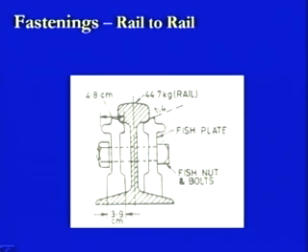In this case, if there is any looseness at this level, whether it is because of the size of the hole or because these nuts or bolts have not been fastened in a tight condition, then there will be a relative movement of the rail sections as soon as there is a load passing over the top of it. So, that is why it is important to have the tight condition of all the 4 bolts which are provided on these fish plates. And we can see that this is a 44.7 kg rail which is being shown here along with its dimensions. In this case, this is a 1:4 slope at which this fish plate is being cut in this size, so that it fits in with this rail section.